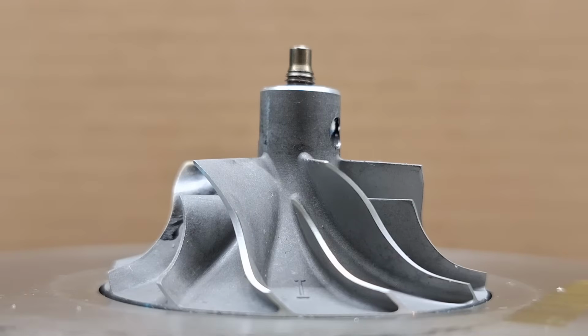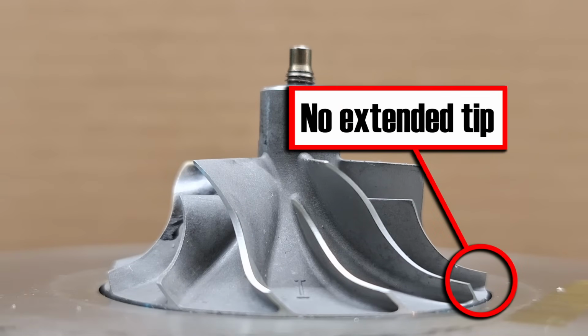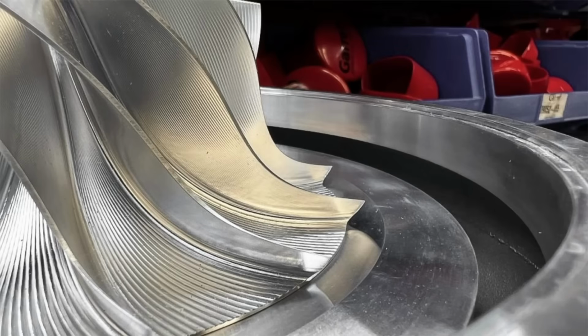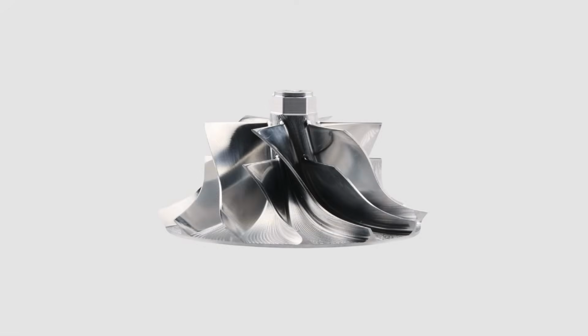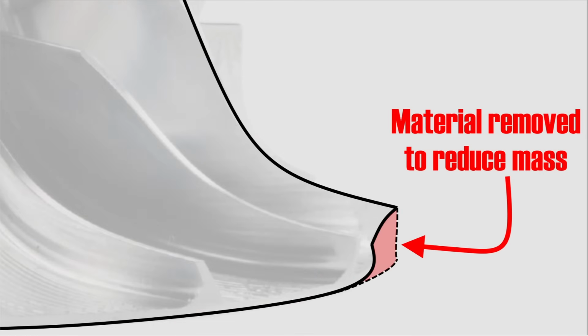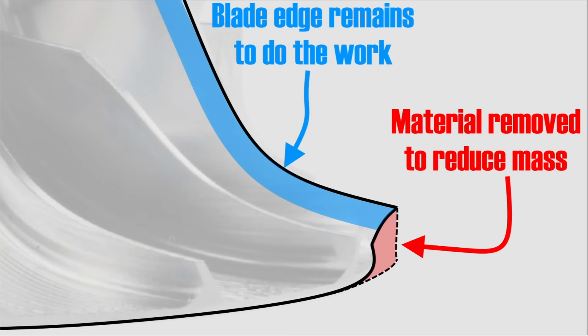A modern and beneficial design feature that this compressor wheel does not have is called an extended tip. An extended tip refers to a special machining technique employed on the exducer end of modern compressor wheels. Material is removed from the very bottom of the exducer but left at the top of the blades. This allows the wheel to harness the improved spool benefits of an increased exducer diameter, but without the added rotational mass which negatively impacts boost lag.